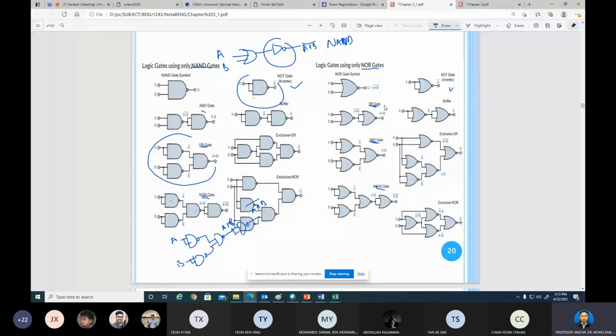Okay, so this is some example. You can change one by one. For example, we have OR here, so you can change that part and then add the conversion into NOT. Okay, for example, another example: what happens if you have AND? So you have to double check. If you have AND and NOT here, actually you can combine them into one, the NAND gate.